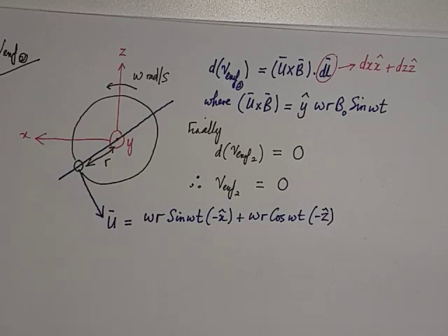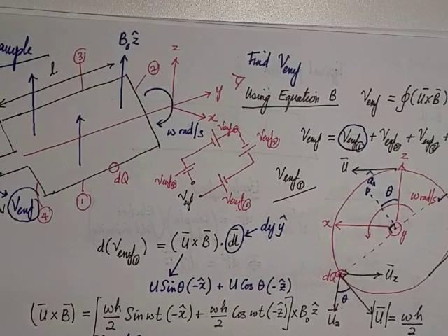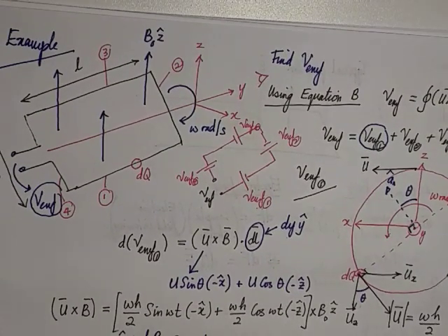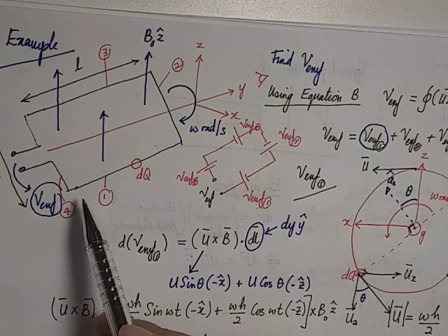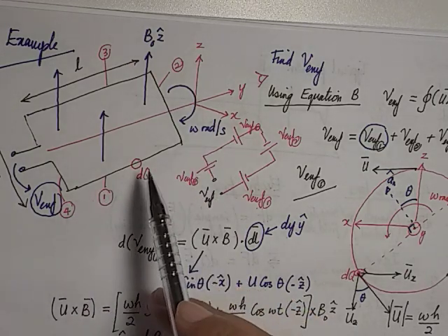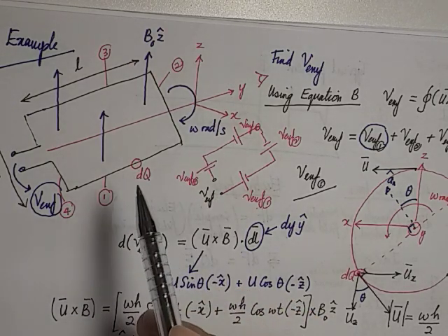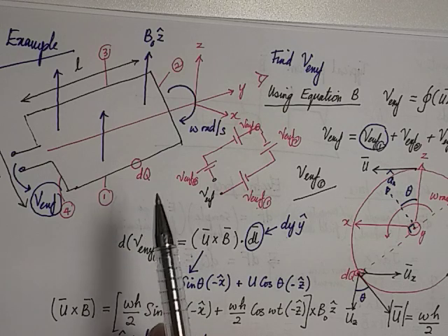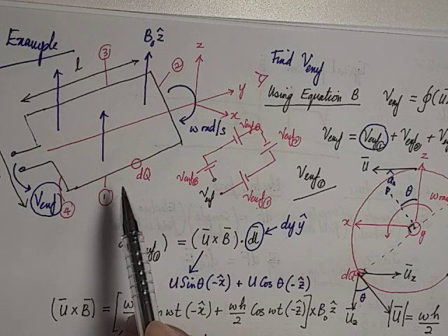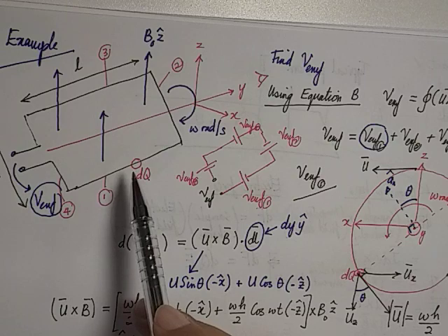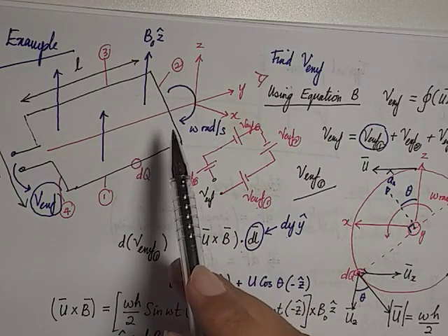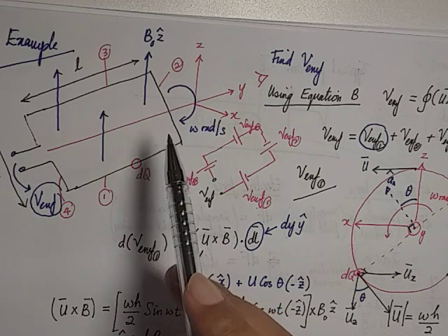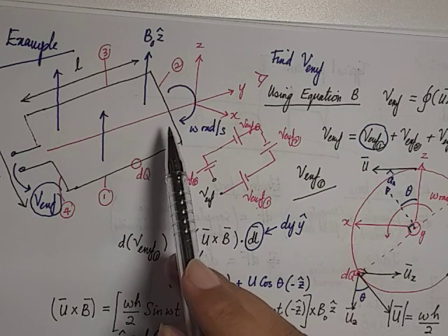So that's why when you look at generator structures, the length is always the side that produces the induced EMF. Therefore, when you look at a generator, it is always long shape-wise, because the width of the generator does not generate induced EMF.